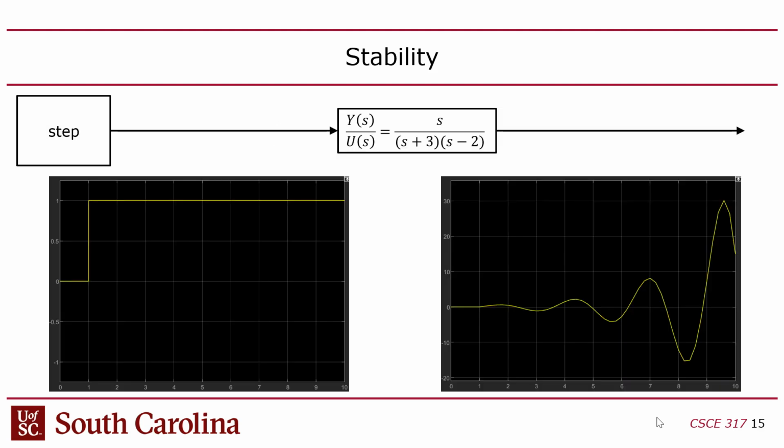The other approach, of course, is you can just simulate it, which I think is also a common approach. So this is a MATLAB Simulink simulation of this thing. So I hit it with a step function in this case, and in MATLAB, you can just create a transfer function. You just tell it what the coefficients are of the polynomials in the numerator and denominator. And then you just hit the simulate button. Well, you have to tell it how long you want to simulate. So I said 10 seconds.